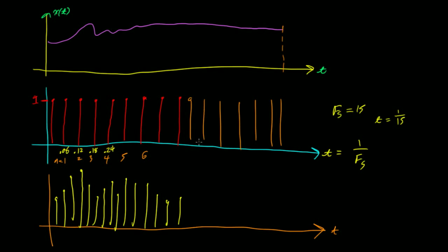Wait, so basically for each frequency, it's going to be implicitly interpreted as a cosine? You can think of it that way. It's a sum of cosines. So if you sample a sum of cosines, certain cosines will be fine, and others will be aliased, because technically you have cosines of up to infinite frequencies. So as long as you sample at a really high frequency, the vast majority of the important components won't get aliased.